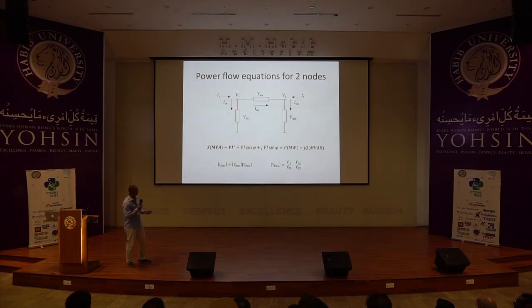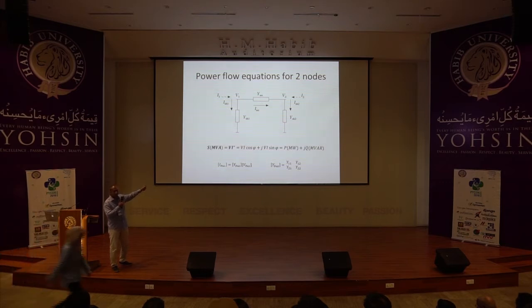Okay, so now that we've seen that, the other thing I want to show is this MVA, right? KVA, MVA, which is your generator's rating, it's in MVA or KVA, right? Volt ampere, which is the voltage vector times the current vector. Okay, when you expand that, I told you it's in the complex plane, so you have that J there. Which in maths is I, in engineering is J. It's the same thing, all right?